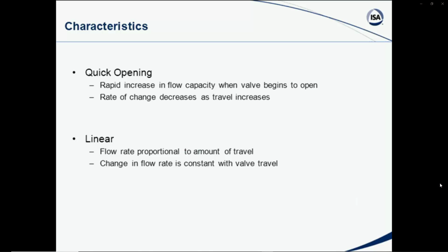So we're going to talk about that a little bit later as we talk about application and the installation or the installed characteristics. Quickly, you'll hear people ask about or talk about different types of valve characteristics. Is it quick opening? In a quick opening valve, the trim is designed such that you get a rapid increase in flow as the valve first begins to open.